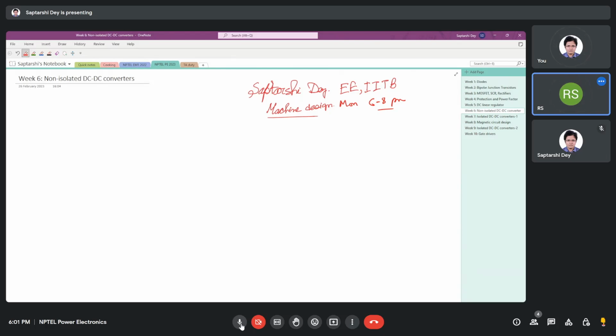Okay. Sir, in the linear regulators, in the shunt regulator, while selecting the output load, the resistance that we can connect, what we are doing is actually we are removing the zener and then keeping the source voltage at Vmin. We are calculating the